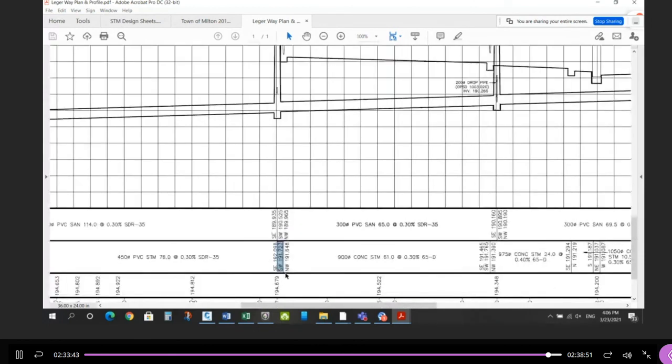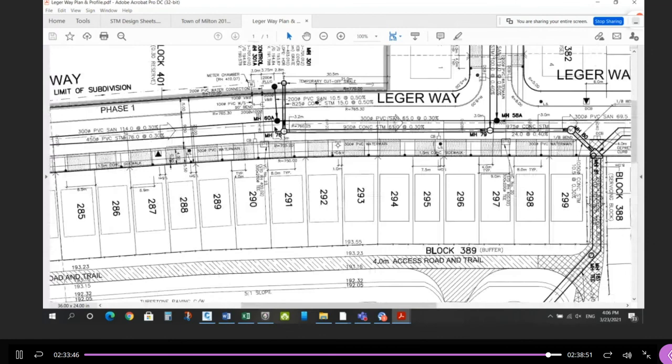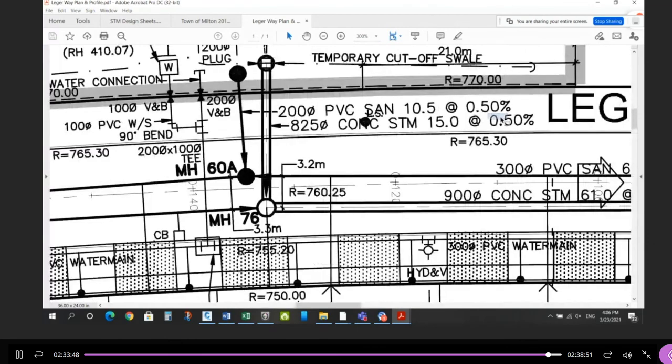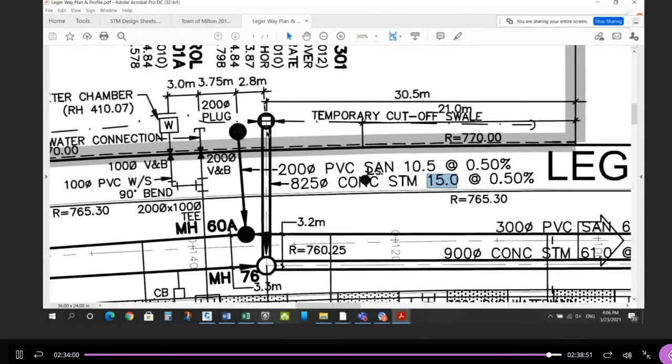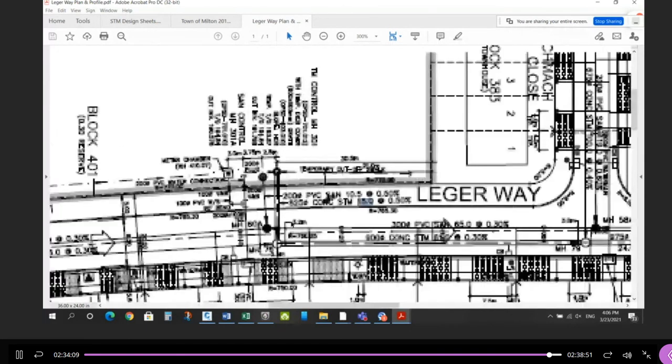right? And then the slope of the pipe is given here. It's 0.5%. So you start with this invert, go up whatever the length is. And again, if you move this maintenance hole, this length, 15 meters, may not apply again, right? So start here, add the length times the slope, get a new invert, add the minimum drop, length times slope, add the minimum drop, length times slope. So work your way uphill, just like you did last semester. So that should be a familiar exercise.